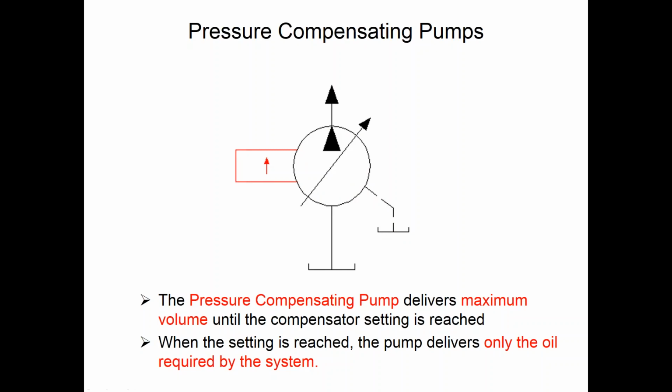We don't do it on most fixed pumps because it's not a problem. A fixed pump is always delivering flow, and if it's bypassing, and of course even a brand new pump bypasses to some degree, whatever bypassed oil goes across the components in a fixed pump will just go back around to the suction side and go right on through the pump. Can't really do that with a variable displacement pump.